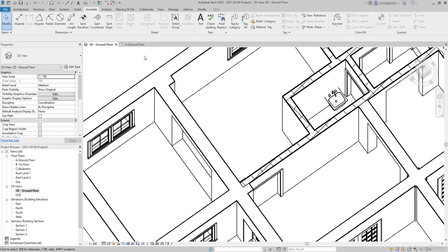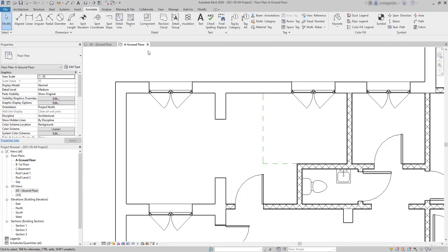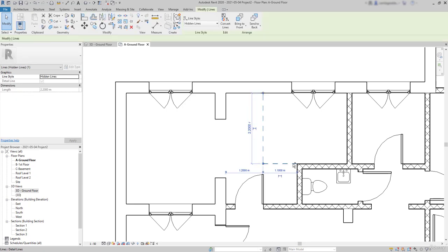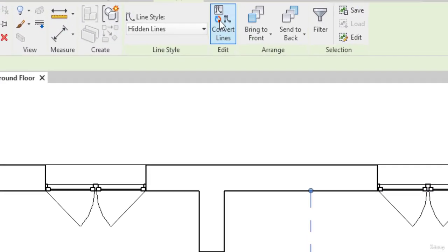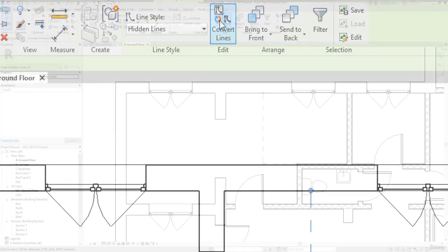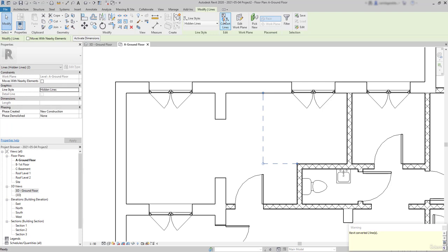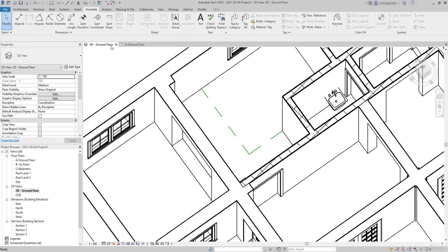Great, but suppose that later I have changed my mind and I want these lines to appear in all the views. Imagine them as a real separation, for example, a boundary painted on the floor, even if it sounds a bit hypothetical. But that's simple. If I select both, at the Modify tab, there is an option to convert detail lines into model lines. Click there, and they will show up in all the views that we have in this file.